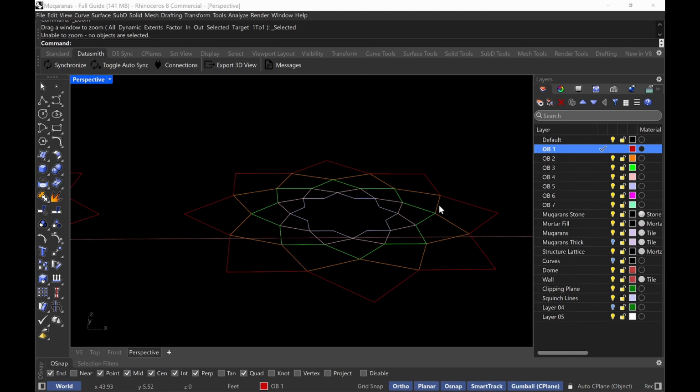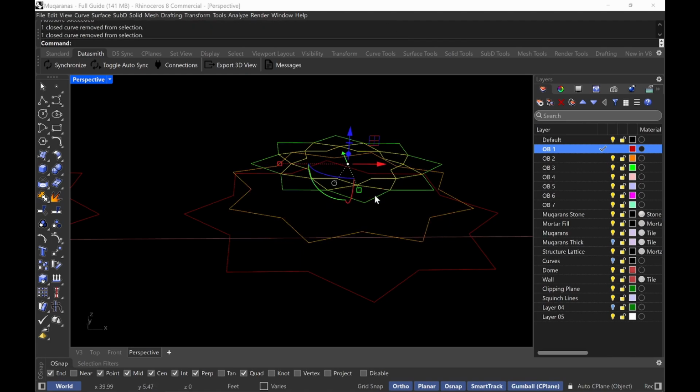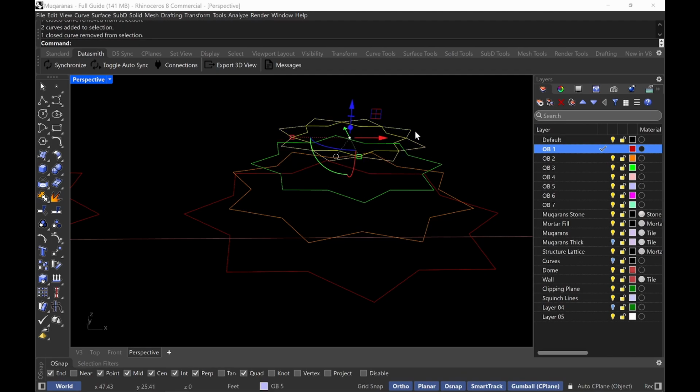Based on construction methods, if you were going to corbel it, like a corbelling method, that's going to be based on the height of your masonry, right? If you're going to do the plaster lattice work method, which again, I'll go into detail later, you can make it any height you like. It just depends on the aesthetics that you're going for. So I'll just go ahead and lift each of these up like 2 feet for now, okay? So I'll just type in 2 feet. I'll deselect that, 2 feet, deselect this. Oops. 2 feet, deselect that, 2 feet, okay.